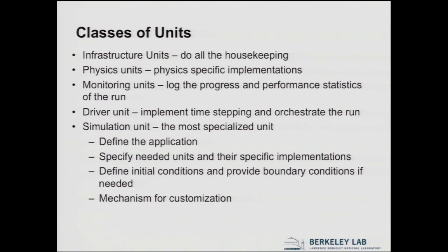The driver unit implements time stepping and basically orchestrates the interactions between the various units, the order in which they should interact with one another, and also manages things like whether you're starting a run from scratch or starting from a restart, from a checkpoint. The simulation unit in Flash is the most specialized unit. It plays many different roles. One is that it defines the application, which means this is where you give your initial conditions. If you have any specific customized boundary conditions, this is where you put them in.